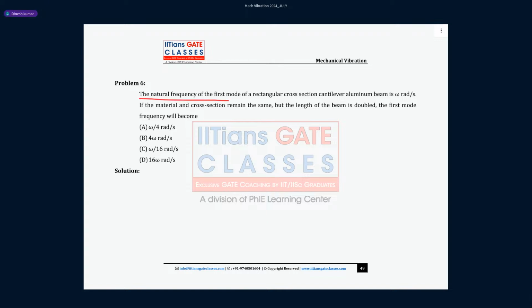The natural frequency of the first mode of a rectangular cross section cantilever aluminum beam is omega. If the material and cross section remain the same, but the length of the beam is doubled, the first mode frequency will become? So guys, we know for the case of the beam, omega is proportional to 1 upon L square, right? Now what they told, the length is double. What will be your frequency?